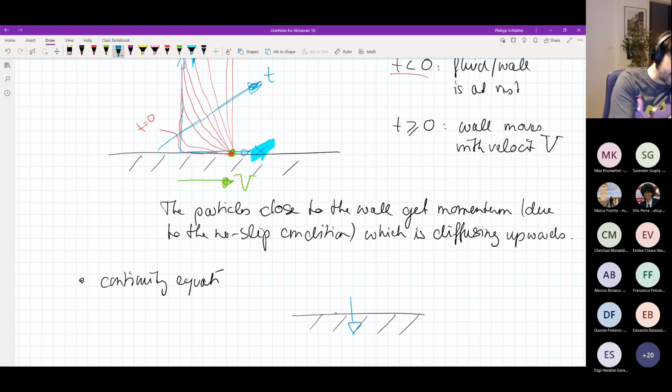But that means also that the flow can actually have any velocity. So this is not allowed. The flow can only go parallel to the wall, but it can have any velocity it wants to have. So there is no no slip boundary condition. That means for an inviscid flow, the speed of the wall actually does not play a role. It will not transfer into the fluid.